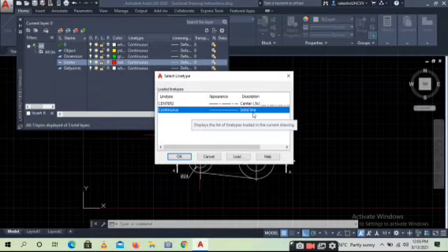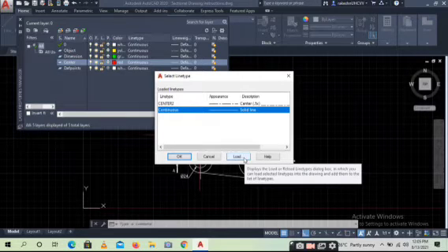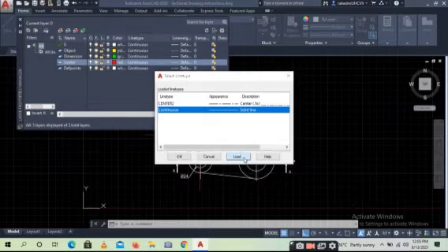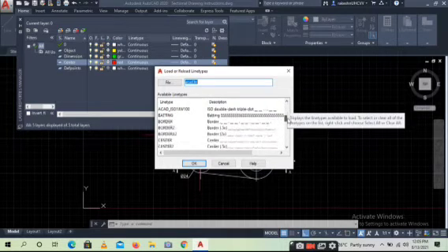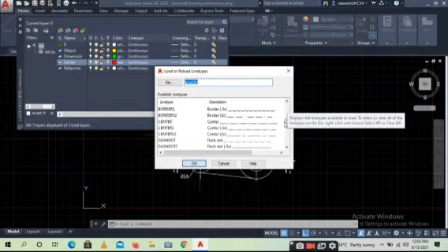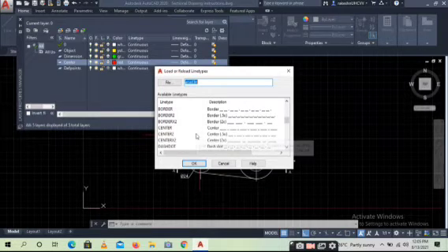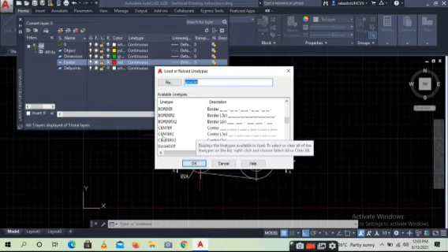To take the center option, there is an option below the pop-up window which is load. You select that, and then you just scroll down. You can see there are different line types, right? In the set of line types, you select any of the center line. Like you have 3 different center lines: center, center 2, center x2, etc. I'm going to select center 2.